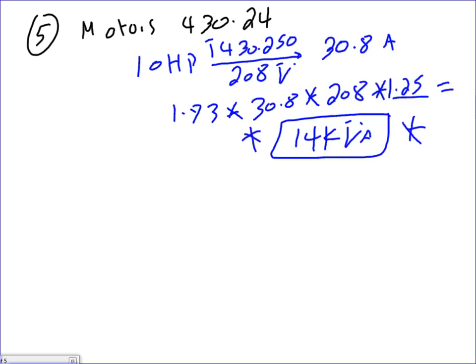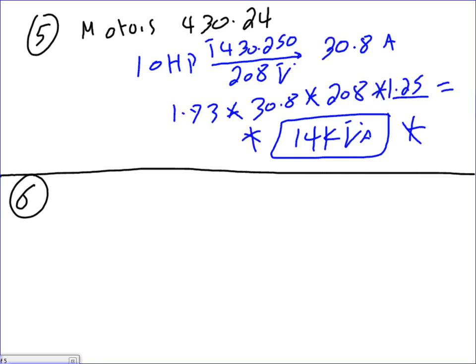In the big scheme of things, that 25% becomes meaningless. When you have an MCC with like 50 motors, adding 25% on the largest motor becomes meaningless, as you're going to see later when you have bigger systems. But let's just leave it. Any question about step number 5? Since I have room, I want to go ahead and do step number 6 if you don't mind. If you go to Article 430.24, it tells you 1.25 times the full load current for a motor.